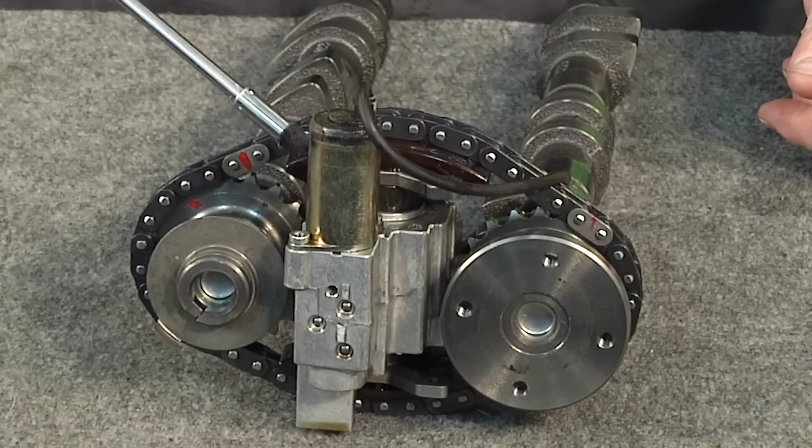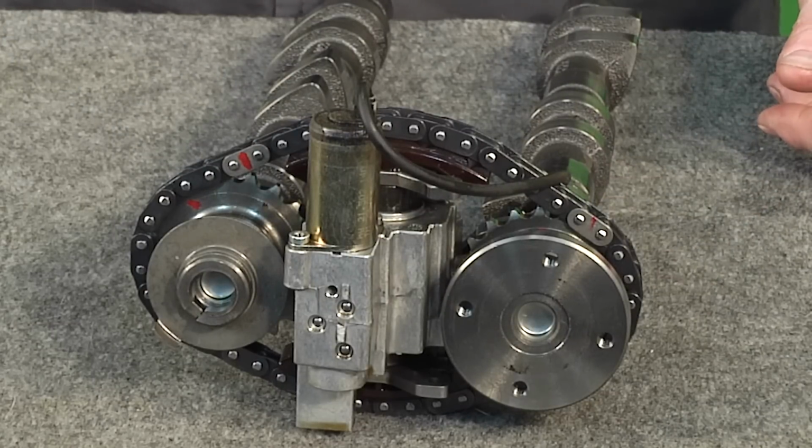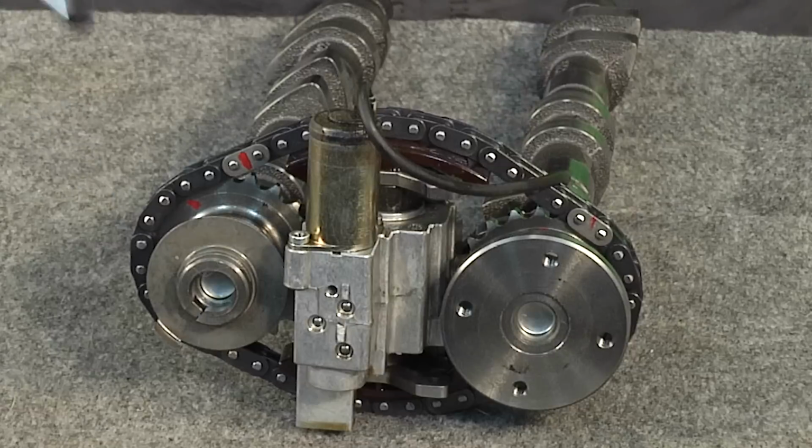Of course, it's going to work just like it does when you change the wear pads. You're just going to end up changing the entire hydraulic unit. I would also recommend replacing the electronic solenoid that actuates it. And sometimes even that electronic solenoid will be responsible for that 25 degrees. So you definitely want to make sure that you diagnose this, make sure you don't have an electrical problem, electronic problem, and you want to make sure that your issue is a hydraulic problem before you replace the entire unit.